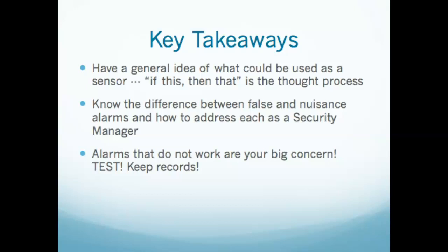Match the door. If it's a swinging door and on a man door, if you will, a regular door, you're going to use a reed switch of some kind. If it's a cabinet door or a cabinet pull, you're going to use a plunger. If it's outdoors along a fence line, you're going to use microwaves. And if it's hallways and open areas indoors, you're going to use a PIR. Those are really the four main ones. Make sure you know how to match those up.